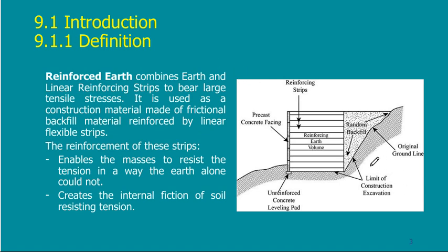So in a reinforced earth wall, it is not only the face of the wall that is carrying the load, but the face of the wall plus portion of the soil behind it, using some kind of reinforcement that would penetrate through this mass of soil, so that they finally would act as one piece. So this whole system will be my reinforced earth. So it is a very good idea.